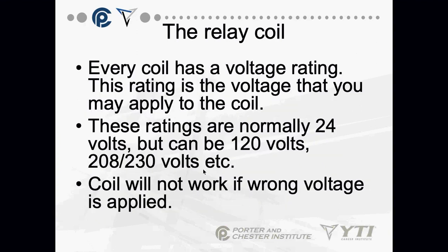Every coil has a voltage rating. When you look at the side of a relay or a contactor, you always see a label. The rating is the voltage that you may apply to the coil. Don't put the wrong voltages on the coil. The voltage rating is the rating that you can apply.